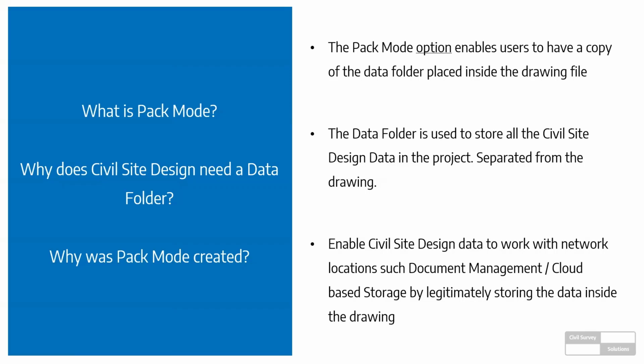You can function as you would normally with Civil Site Design, with your data folder next to the drawing. So this is an option which you can choose to operate with, and you're going to see the benefits as to why you may choose to. You'll have the option to copy your data folder and have it compressed and placed inside the drawing file. As I said, we're going to show you how this whole process works.